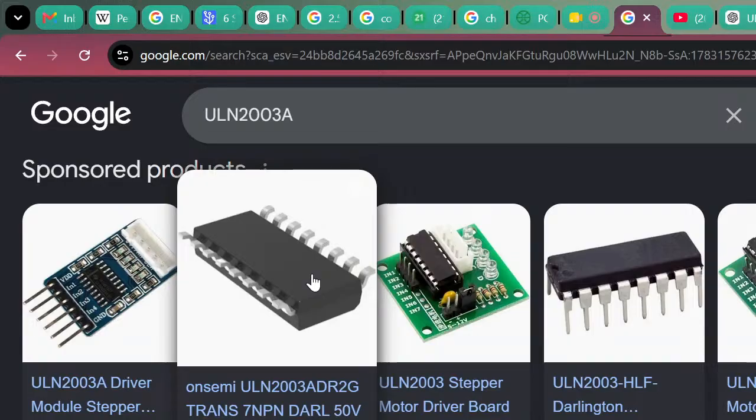In relay modules, we discussed the construction mechanism, how relays work. It is made up of a coil, which is nothing but an inductor coil, and we have normally open and normally closed pins. Along with that, we discussed the armature, which is the movable part. Whenever we apply a small voltage to the pins of the coil, this small current produces a magnetic field.